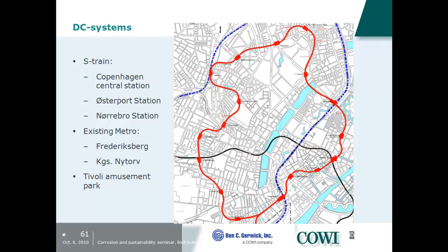They know that themselves. They have had a building in a part of one of the stations that blew up. A fire took place because they had an arc. They had some stations where they gave up on surveillance at one of the city stations because stray currents were short-circuiting that camera all the time. So they do have problems. And they operate at another voltage level. It's a floating electrical system, so they are not grounded to the same system. Therefore it has another potential than the future metro will have.